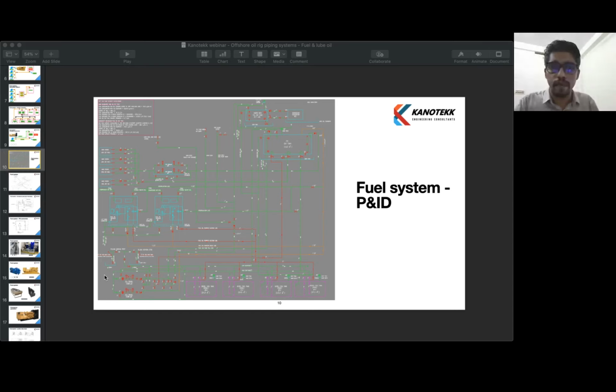There is a question asking for the pump details of the transfer pumps. As stated earlier, transfer pumps are gear type pumps, due to the viscosity of the fluid. For fuel systems or lubricating oil systems, generally gear pumps are preferred. These pumps will have a relief valve system to maintain the system design pressure. The capacity of pumps generally varies. Usually we provide 50 gallons per minute. It can go higher also. For high flow rates, as stated earlier, we will have to use centrifugal pumps.